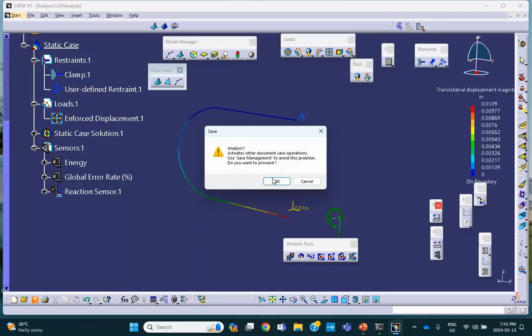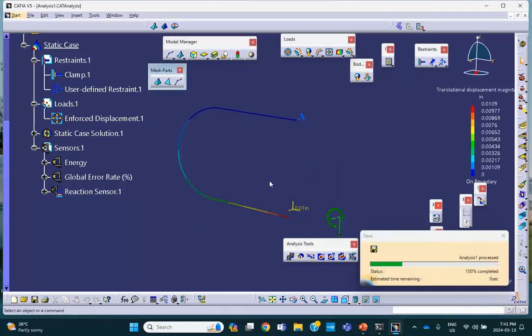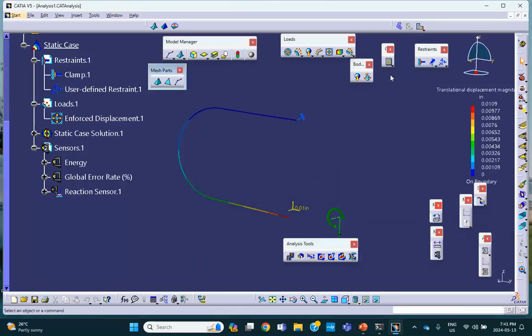So you repeat that problem using beam element. Now notice that the only issue is that we cannot plot von Mises stress in beams. Okay, you can plot the principal stresses, but that's totally useless. Okay, so there. All right, let me close this and close that.